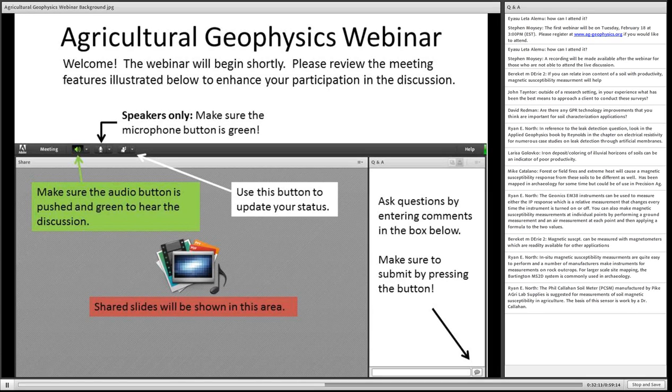Ryan North just posted a comment, I'll release it to everybody, saying he's been using his 3D Radar GeoScope system for high density mapping of large areas. The system is 2.1 meters wide with 25 channels at 7.5 centimeter spacing between the channels. It's a continuous wave step frequency GPR. And I think that's one of the exciting things coming down the line for people interested in detailed mapping with GPR: these multi-channel, ultra-wideband systems that were originally developed for things like landmine detection and utilities detection. So sorry to step in, but I'll release it back to the speakers.